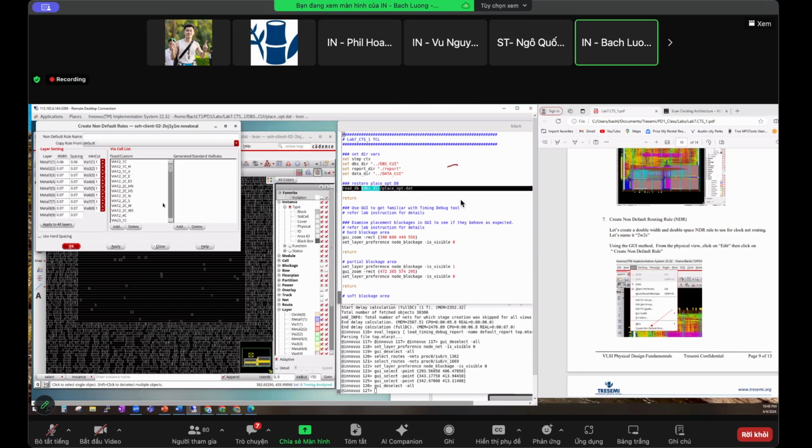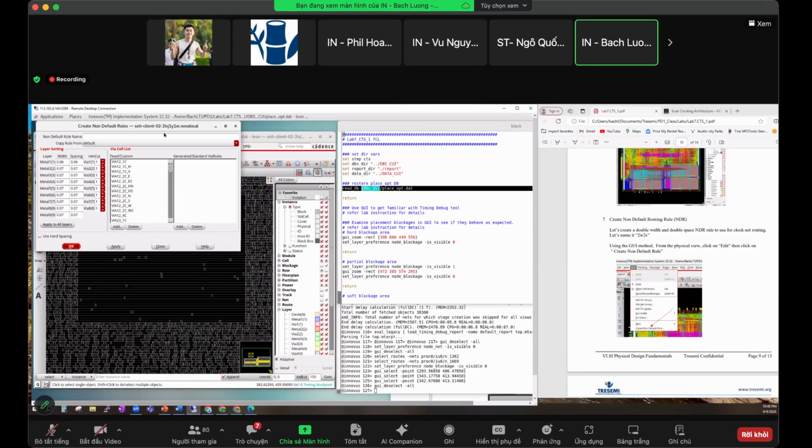Okay, I normally don't do it this way. I use Tcl to do it. But this is what you can see come up. It's just a single width. We have 9 metal layers. This is the width of metal 1. This is a single width throughout. So in this technology, it's 0.07 micron for metal 2 through 7, and spacing is the same.